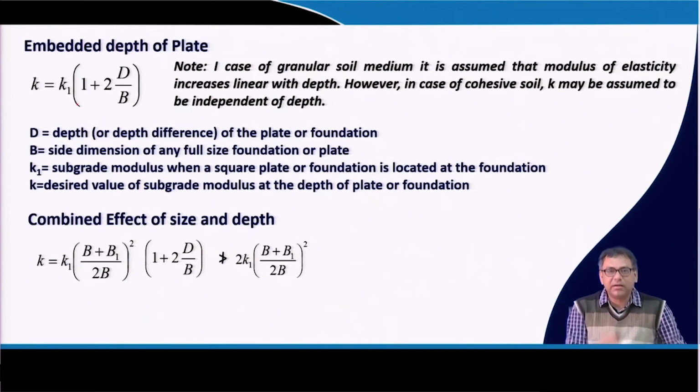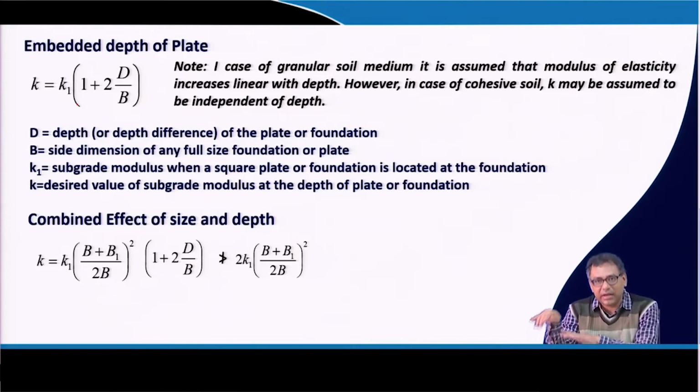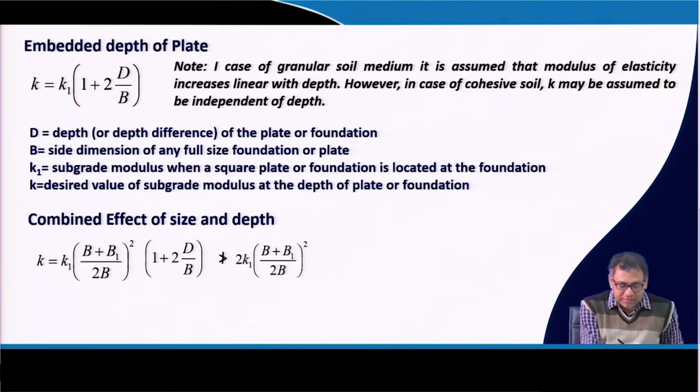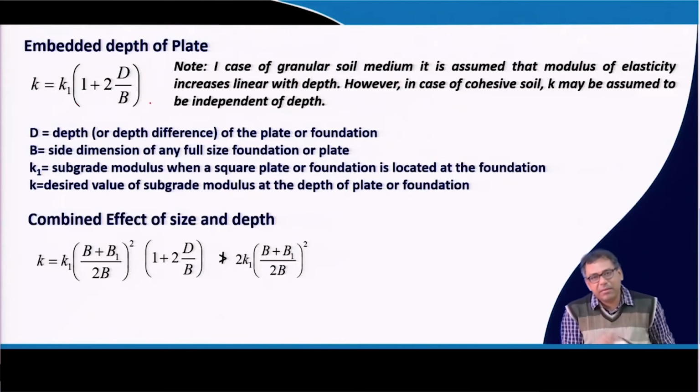Now, the third thing is the depth of the plate. Ideally your depth of foundation and plate depth should be the same. If both are the same, then no correction is required. But suppose you have done the test on the surface of a soil and you have placed the foundation at a certain depth, then you have to apply the depth correction. So, how we will do that? So, this is the correction factor, and remember that